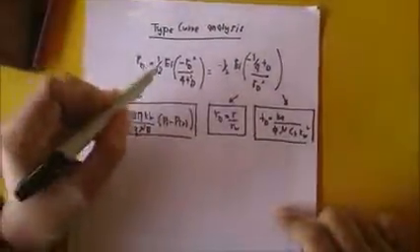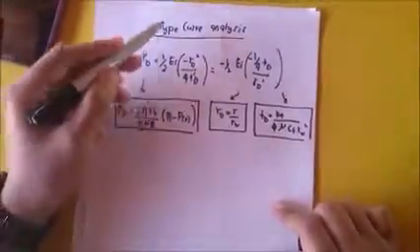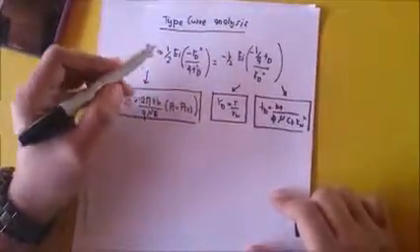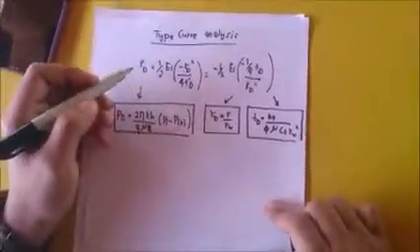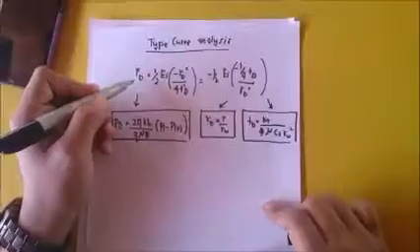So a more convenient way to analyze such tests is using type curve analysis. To use type curve analysis, we need to solve the equation in dimensionless form. Here is the equation in dimensionless form.